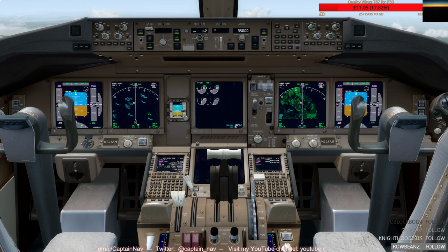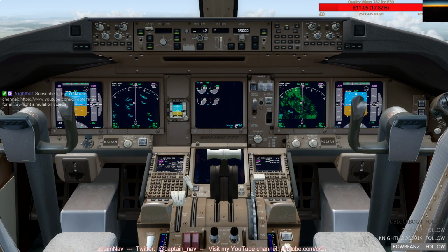So I think higher up, more like VNAV, because VNAV has calculated the whole descent profile, and initially it's putting you into a reasonable place to follow the VNAV profile. But then further down, from mid descent onwards, flight level change and vertical speed give you more control over the descent. And as I said, once you leave the arrival itself because of radar vectors or shortcuts, those two modes, vertical speed and flight level change, are a little bit better.